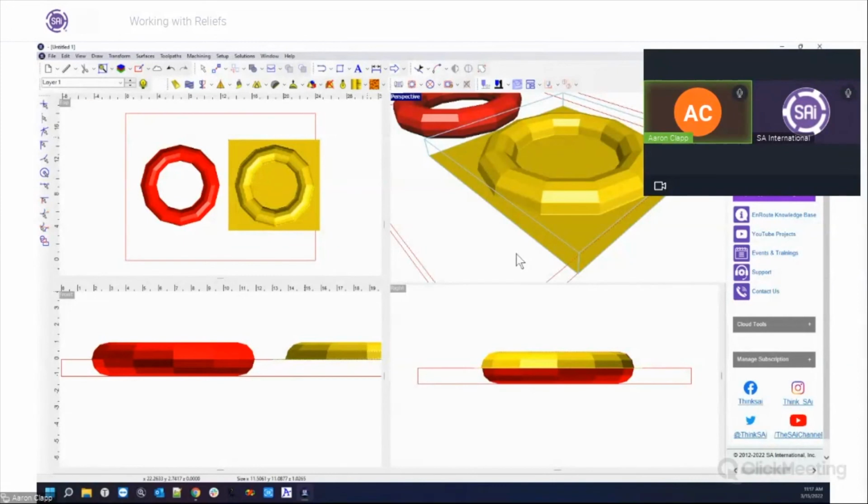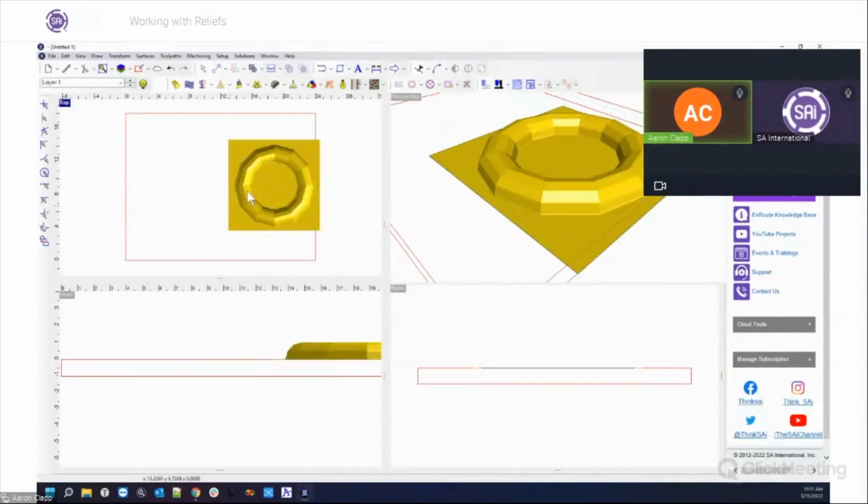You would just do the chamfer on the top side, and then you'd copy that entire thing, and do the same thing, but with a contour for the bottom side. So basically, you'd create one contour, split it in half, take the bottom side of the contour and chamfer it to one side, and then take the top side, chamfer it to another object.